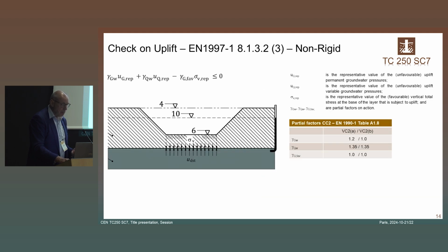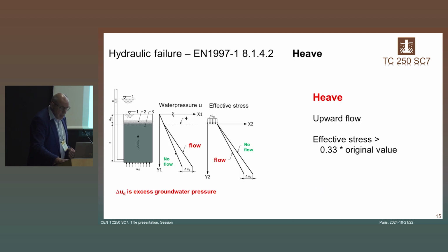The other case on uplift is where you don't have a caisson, but an excavation, where you compare not forces, but pressures. You have a vertical pressure of the ground against the uplift pressure of the water. Well, and again, the partial factors.